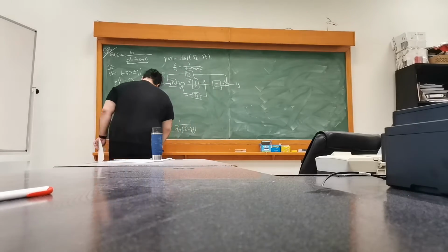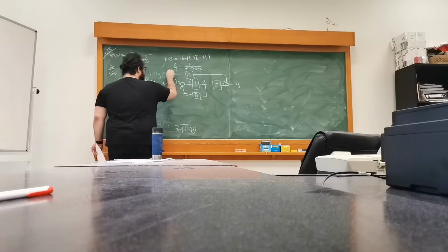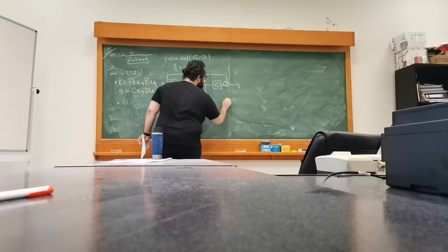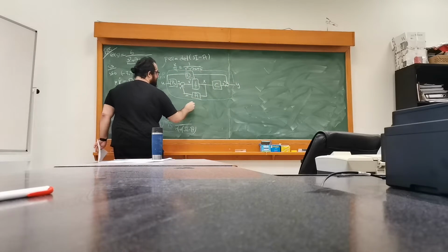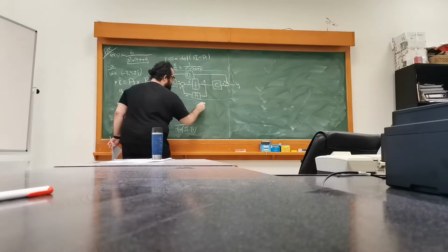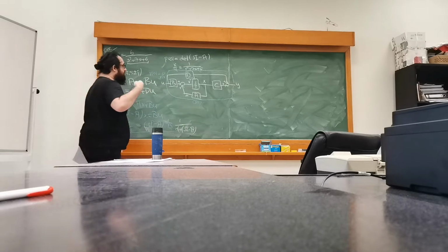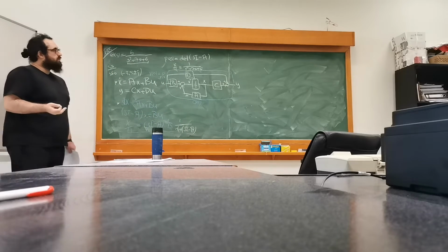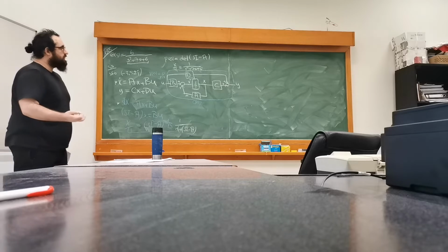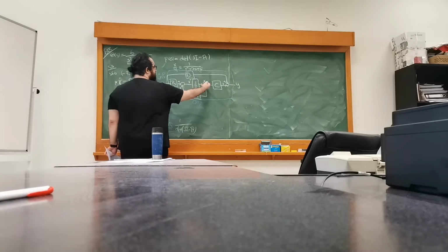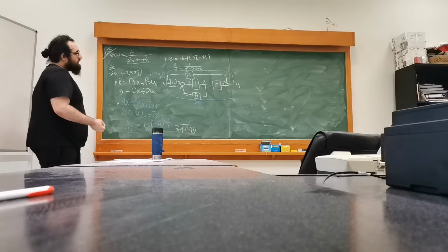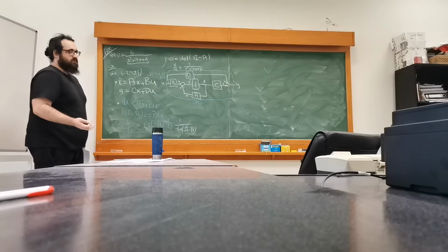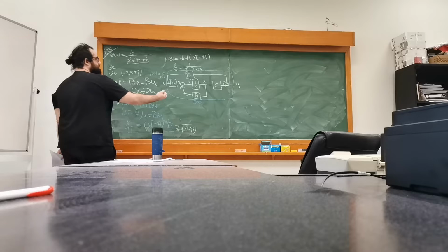But my whole transfer function here is the relation between the input and output. But I'm using the state space model in order to generate internal signals like x, the state space variables, in order to model it in more detail. So I have access to its internals.